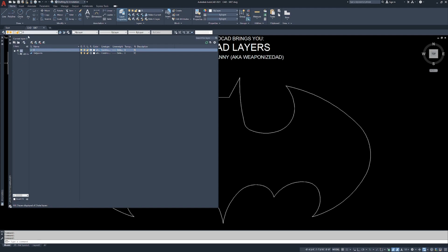You can actually lock the locations and how you have your CAD window set up. So the ribbon you're not going to be able to move around, but these toolbars that we added can be locked in position so you don't accidentally grab them and drag them out into the model space. If you notice when I try to click on the dots, it's going to give me a red X and essentially say, no, you cannot move that toolbar. Same thing with the dockable windows. If I try to grab this Layer Properties Manager, it's going to give me a red X.